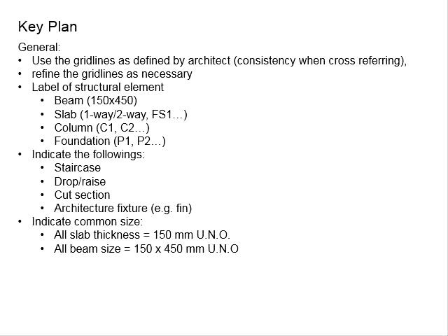Next, in this video, we're going to discuss further about the key plan in terms of what kind of information you need to incorporate in the key plan, as well as some insights related to the key plan. First, your structural key plan should be on the basis of the architectural drawing, as you need to derive from there, and the layout of your beam and the size of your slab will be very much dependent on the layout of the floor plan given by the architect.